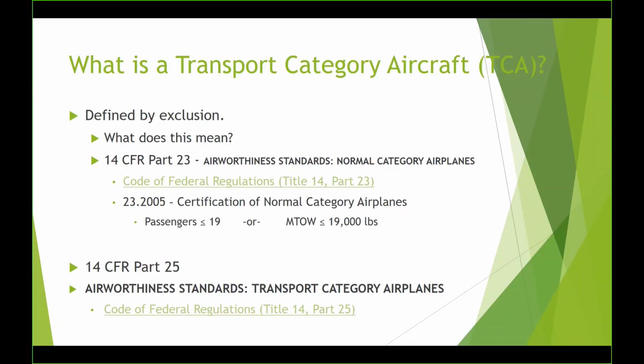No, that's passenger. However, you've got to know what the flight crew is certified as. Some aircraft are single operator, some are 2 crew. A straight wing Cessna Citation can be flown by a single person, so the right seat is technically a passenger, but none of those are going to be over 19 passengers anyway. Anything that carries 19 passengers is going to have a minimum of 2 crew.